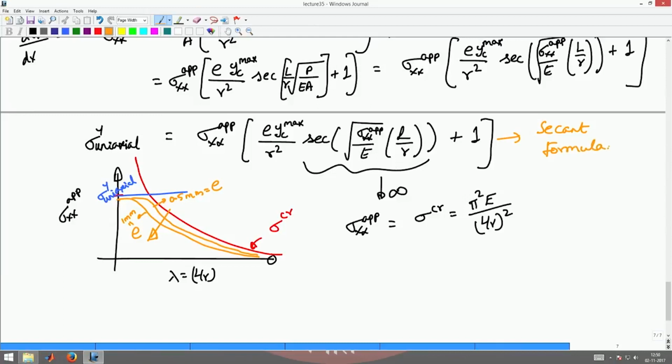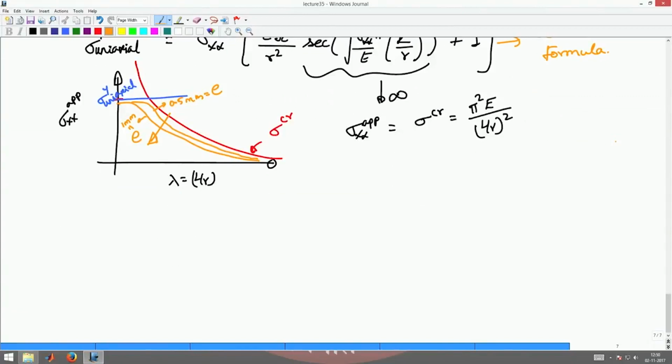Okay. Now, there are other variations by which you can generate realistic behavior. The other possibility is, instead of applying an eccentric load, it can be just like what we did for the equilibrium. You can give a disturbance wherein you have a simply supported beam, wherein you can say I applied a lateral load W like this.